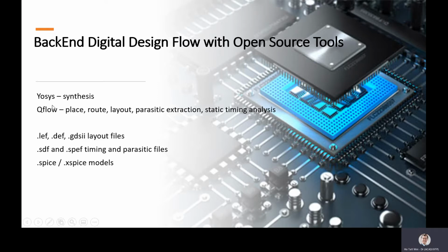This will be done with the software called Yosys, followed by placement, routing, and layout using the Qflow suite of software, as well as extracting the parasitic resistance and capacitance from the layout of this design and performing the static timing analysis.